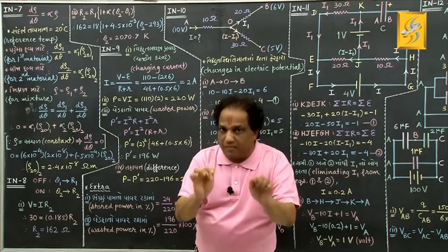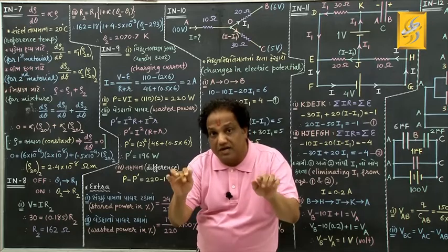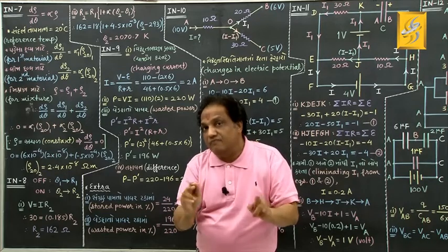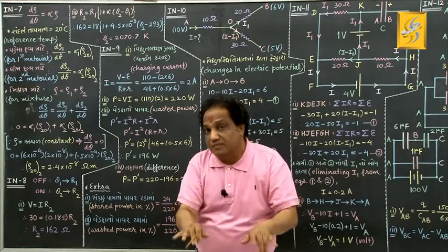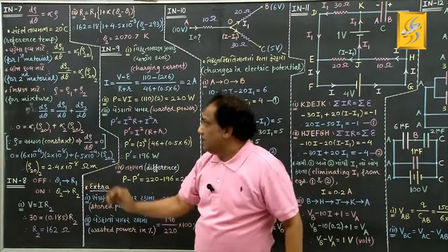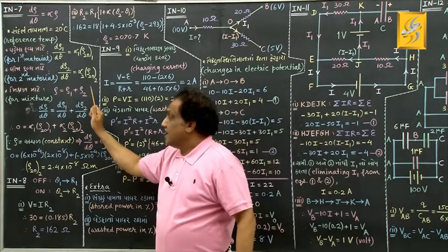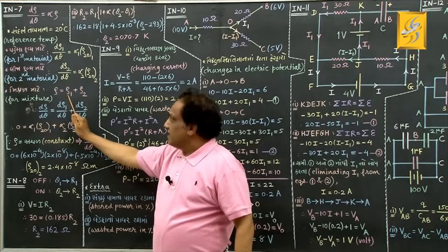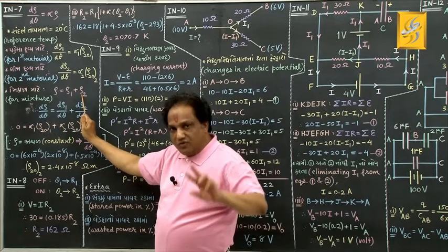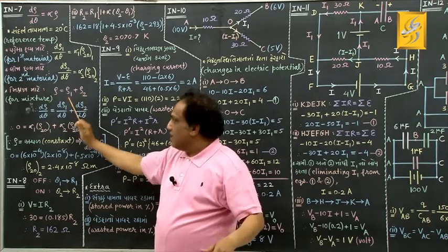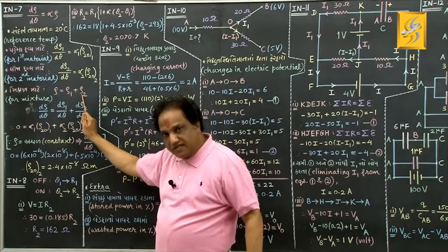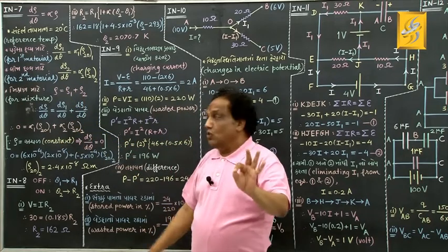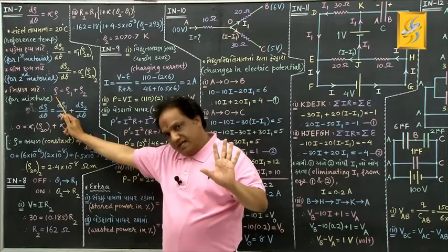But because the temperature coefficient of resistivity for the second material is negative, when temperature increases, the resistivity of the second material will decrease by the same amount. Ultimately, this summation will remain constant. When this increases, this decreases. Conversely, you can say, when this decreases, this increases, correct. So, I mean to say rho will remain constant, correct, fine.